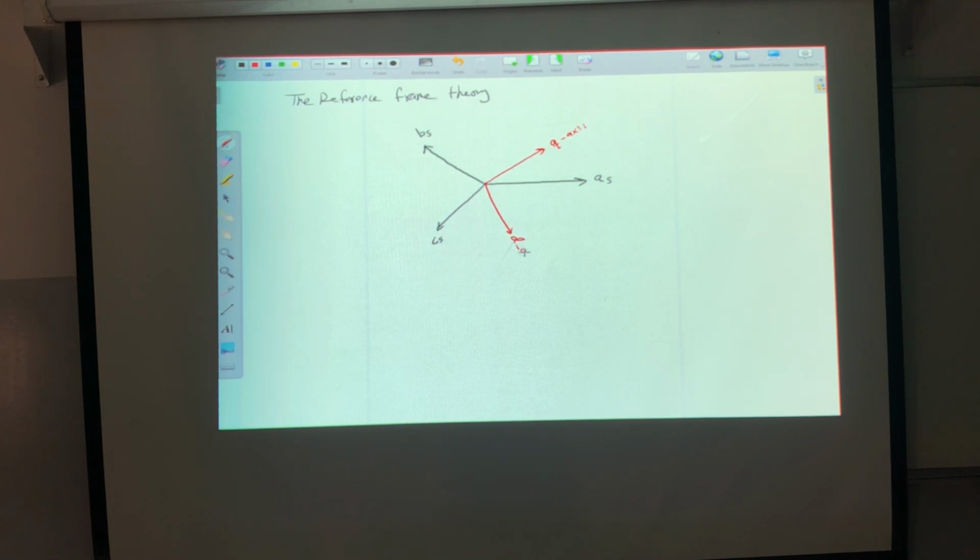Why do we call it the qx and the dx? Simply, the dx is the direct axis. Later on, it will point to the direction of the flux. The qx is the quadrature axis, 90 degrees from the dx. Later on, it will be the torque component. So here it is 90 degrees, which is pi over 2.